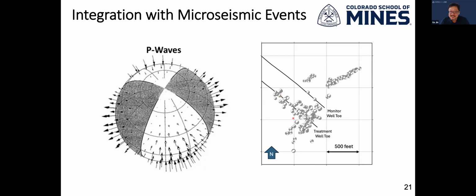In this case, we see a lot of these half-moon events seem to be along the fiber direction. One solution is they have a shear fault perpendicular to the well that is along the hydraulic fractures, which in most cases we interpret as dip-slip events. However, we argue in this case, these events actually represent bedding plane slippage.